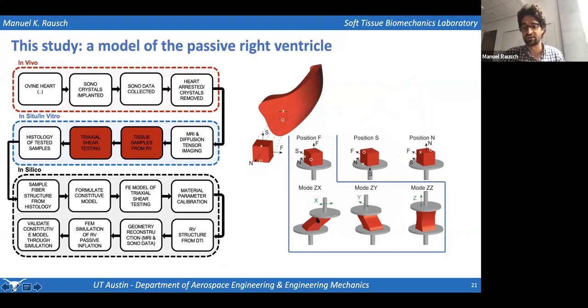And so we can now shear that in one direction, in another direction, and then do constrained uniaxial tensile and compression tests. We remove that same sample, carefully remove the glue, reorient the sample, and repeat those 3 tests, and then we do this one more time. So we test these samples under 9 modes, and we measure forces in 3 directions when doing so. So at the end of this test, we actually have 27 force displacement curves on this one tissue cube.